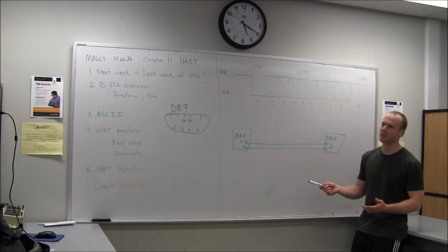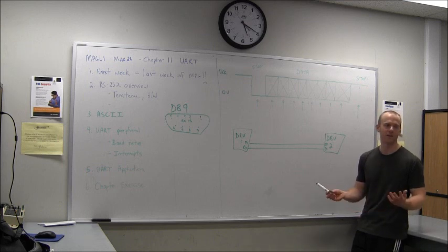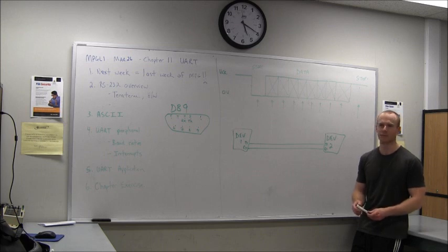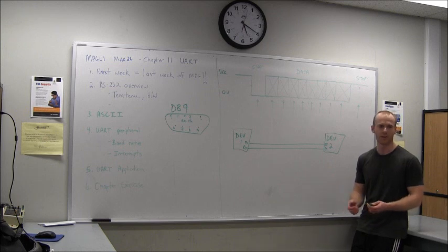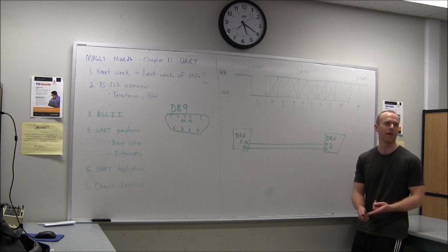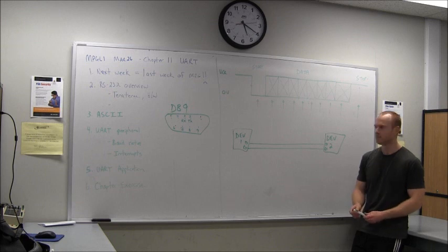If you're not sending a lot of data, 9600 is a great frequency to use. It seems to be somewhat standard for everything you use. A lot of devices do use UART still, so every GSM module and every GPS module that I've worked with has UART as a standard interface, and they usually default to 9600 baud.